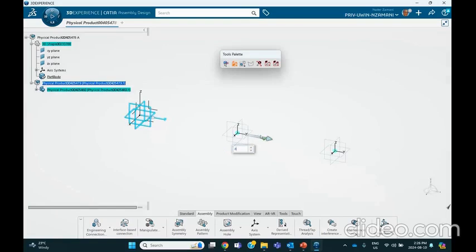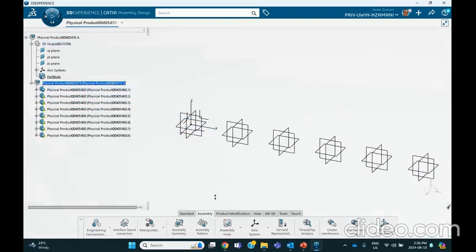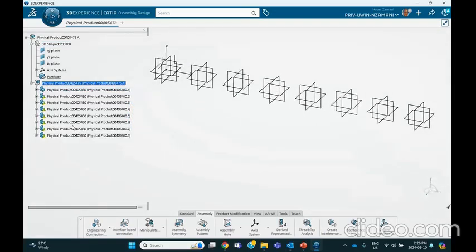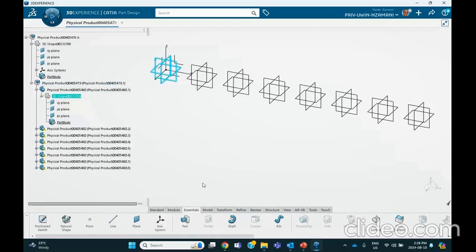And you can change the spacing if this is bothering you. I can change the spacing, but I'll leave it the way it is. And then when you're done, you just left click and it's going to create 8 basically 3D parts, except that I haven't done anything. So I'm going to make my 3D part in this first one. I'll just go to the first one, double click on 3D shape, and then I make one. Because these are replications of that, multi-instantiation, whatever I do here is going to be repeated there.